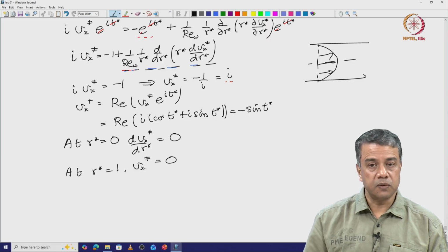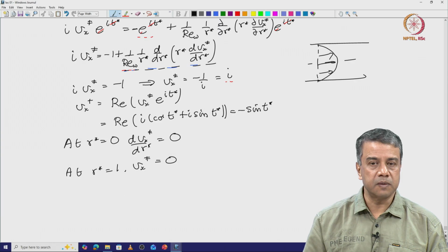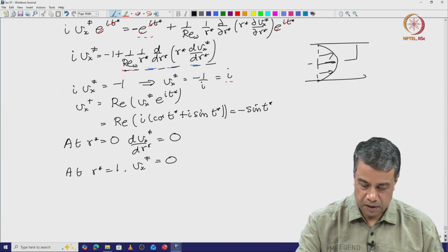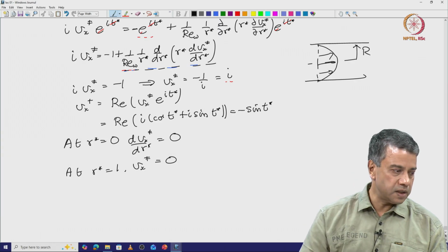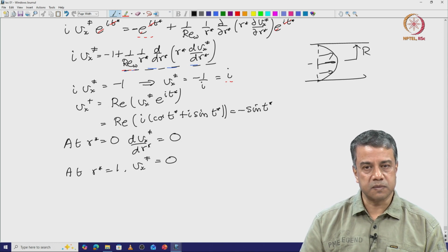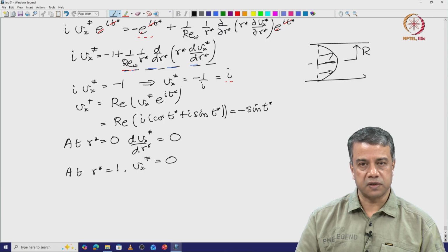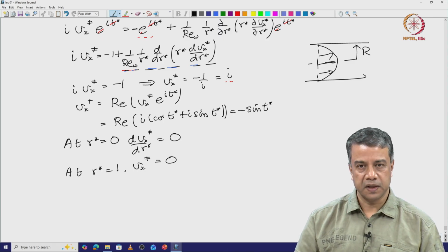Now, what does Re omega large mean? It means that over a length scale comparable to the pipe radius r, momentum diffusion is much slower than convection, or acceleration.